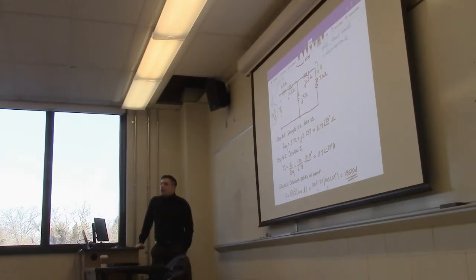If you want to nullify that Q, placing something in series is not really going to help, right? Because a series element is not going to allow, right, we have the current flow along, KCL dictates that the current flow along that line is not going to change, okay? So a series element is not going to allow a reversal of the direction of the Q.